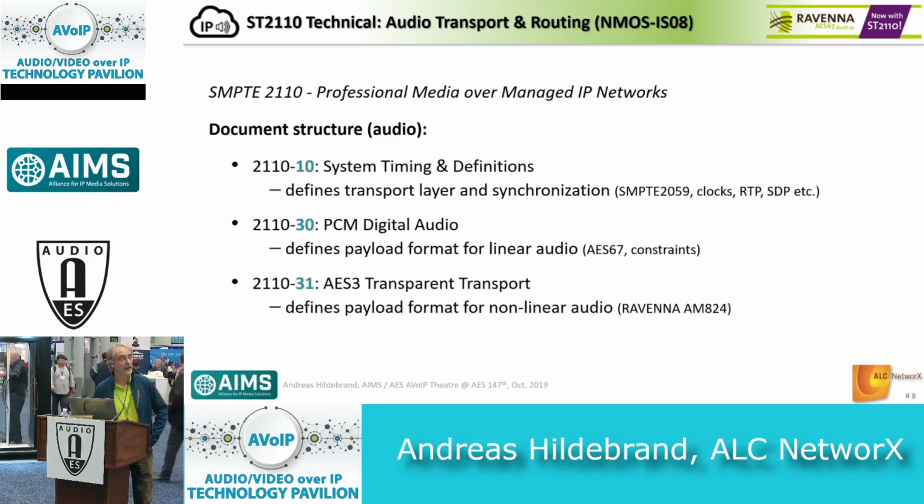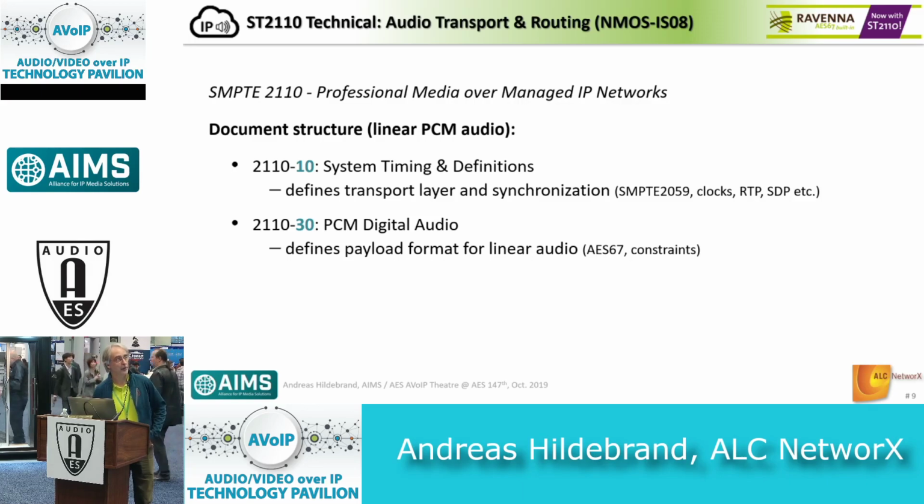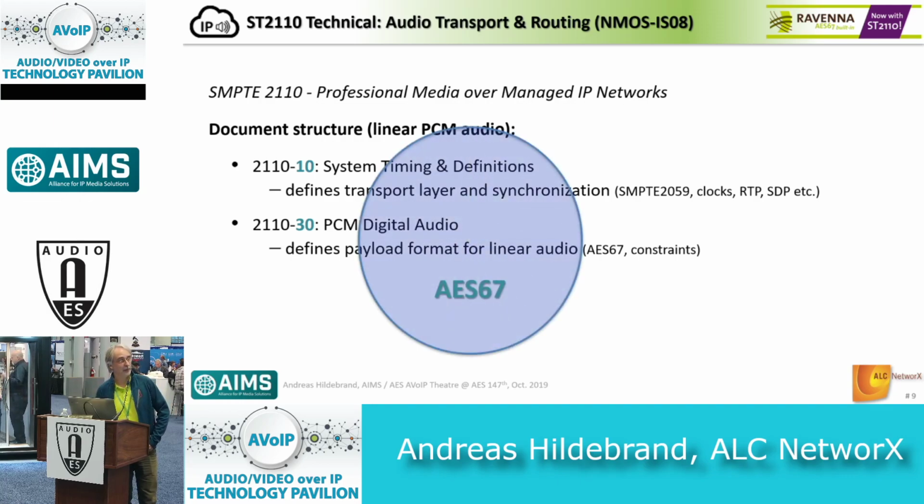So let's have a quick look at the linear audio transport, the -30 document first. So -10 and -30 are required to transport or to understand how linear audio is transported in an ST2110 environment. Actually, what we can say is everything defined here is the very same thing which has been defined in AES67. So SMPTE deliberately picked up on AES67 and said, okay, that's a nice audio transport standard. We take this as the basis for transport of audio in 2110.